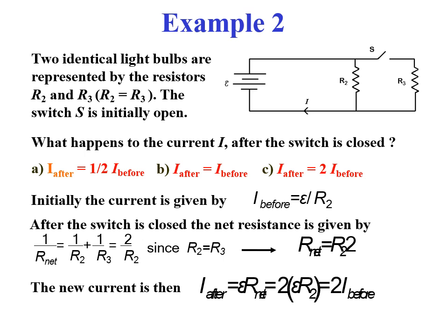Once resistors 2 and 3 are connected in parallel, 10 and 10 in parallel, what is the effective resistance? It would be equal to 5 ohms. So if the new resistance is 5 ohms and you're still supplying 20, 20 divided by 5 would be equal to 4. So the current from 2 amps is now 4 amperes. So what is the answer? C, 2 times the current before.